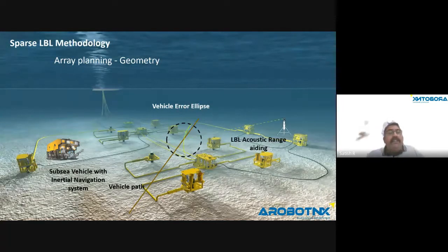First, identify where you want to put the transponder. Then make sure you have a solid angle of cut. These terminologies are derived only from OEMs. When we had a training, this is what the OEM taught us, that these are the things to be considered very seriously during planning. But again, methods will vary. Once you have the angle of cut, there will be a question of what angle of cut you are looking for: 60 to 120.